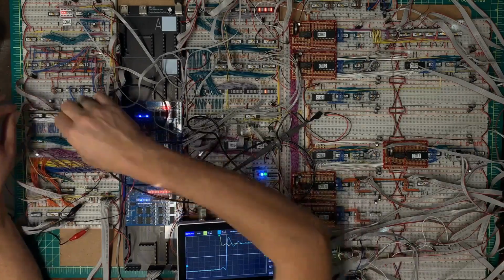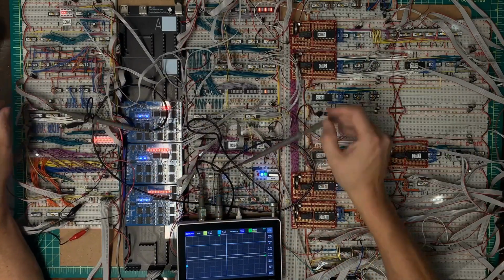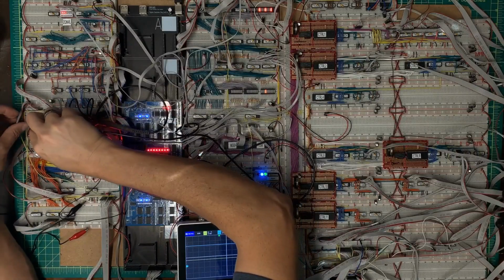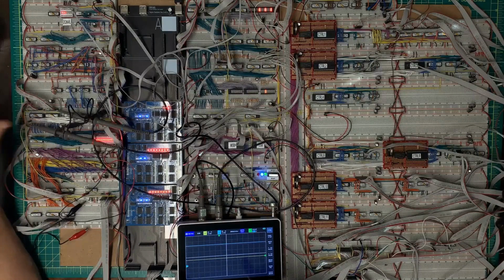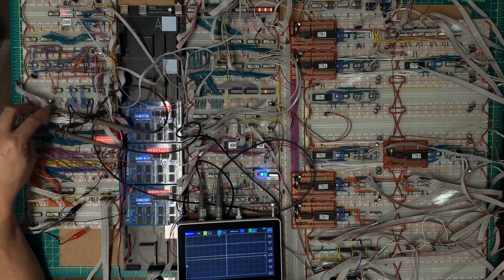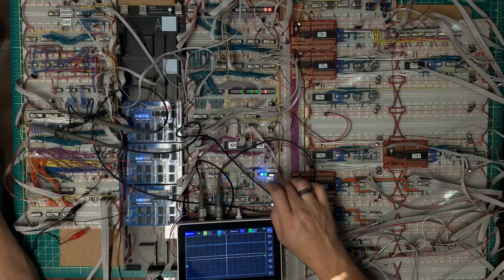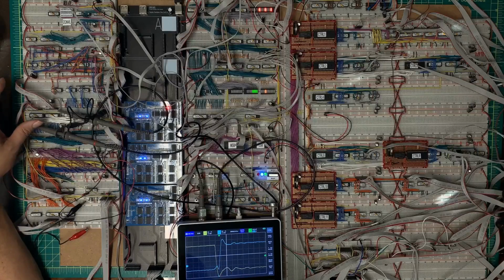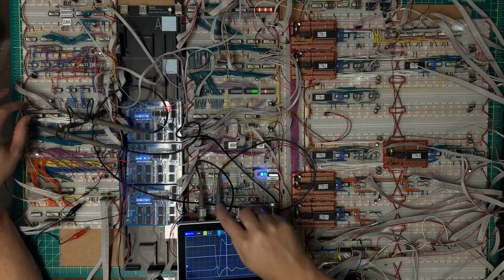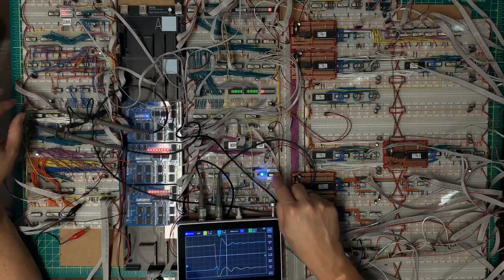Okay, now I want to take and compare the latch against the output enable. I'm really not too concerned with that, other than I want to make sure that output enable is not going away before the latch gives up. So the blue trace is output enable, and it is going low before the latch itself. So theoretically, I am outputting the old value, and then I'm latching and outputting then the new value after that. So that should theoretically be good.